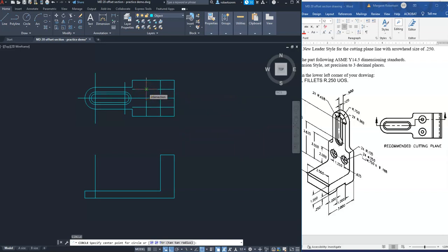Now I've got my intersection O-snap turned on, so I can click right there easily. And because I wasn't that bright, my circle command is the one that says radius. I don't want that. I want diameter. So I'm going to type D for diameter, or I could click right there. D, enter. And what do I want the diameter to be? 0.75, enter.